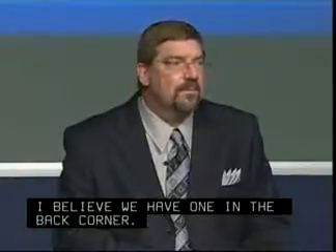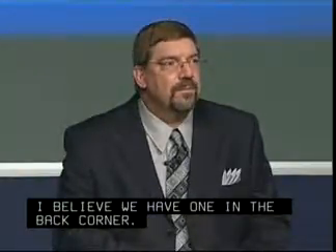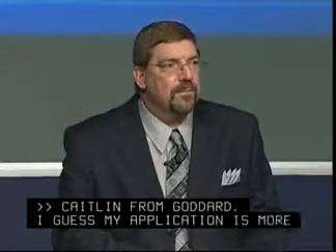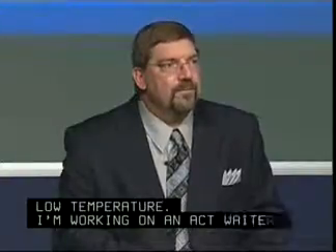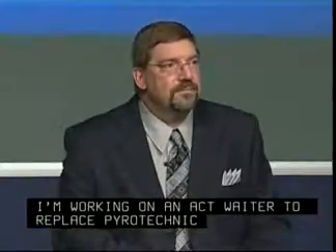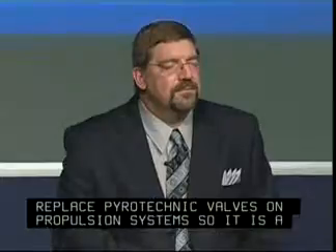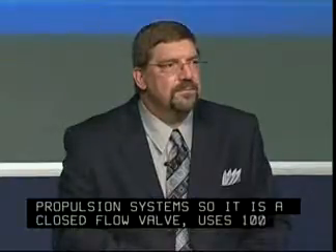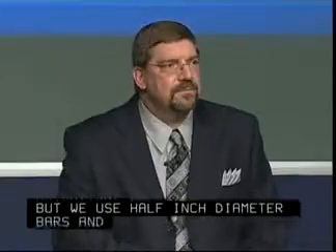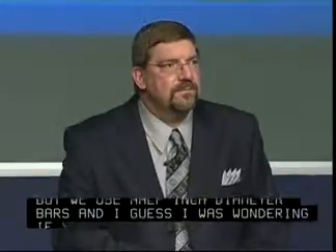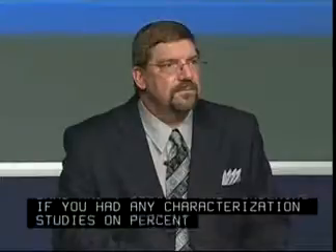Caitlin Eubank from NASA Goddard. I guess my application is more low temperature. I'm working on an actuator to replace pyrotechnic valves on propulsion systems. So it's a normally closed flow valve, uses about 100 C actuation, but we use half-inch diameter bars. And I was wondering if you had any characterization studies on percent recovery and force produced from bars versus wires in the low temperature regime.